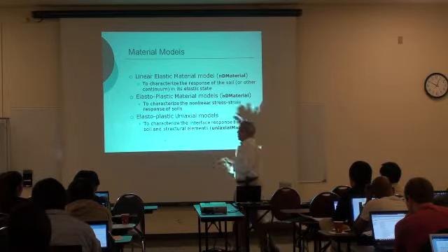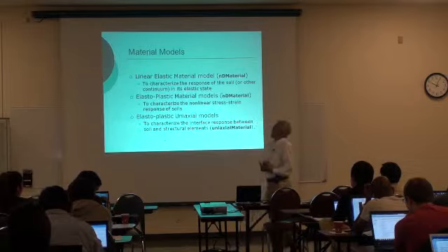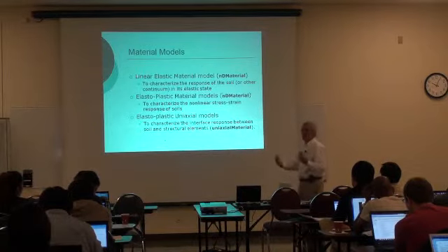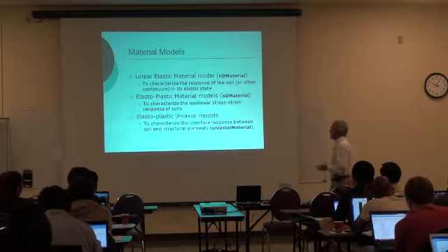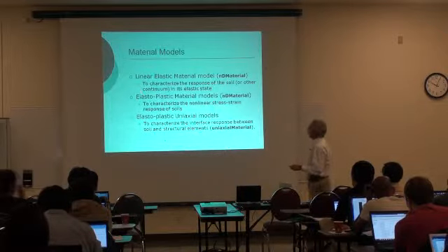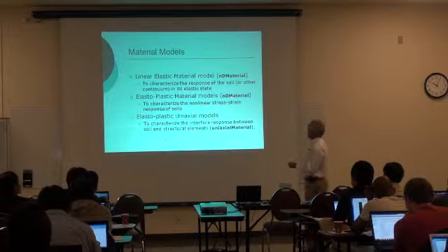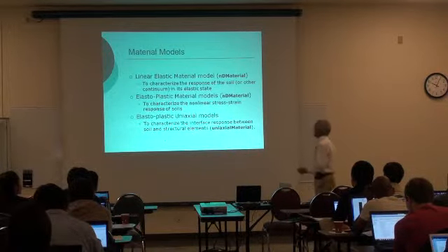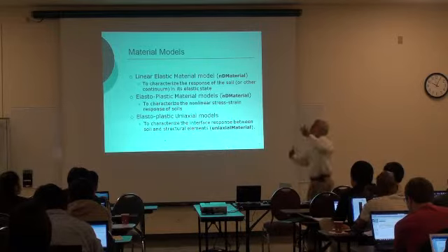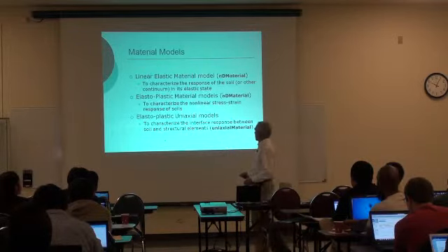Now, we know that the soil is not elastic. So in general, we are very limited using this material model. Now, in order to go into the plastic regime, we have to look at elastoplastic material models. They are still ND materials, and they are used to characterize the nonlinear stress-strain response of the soil.